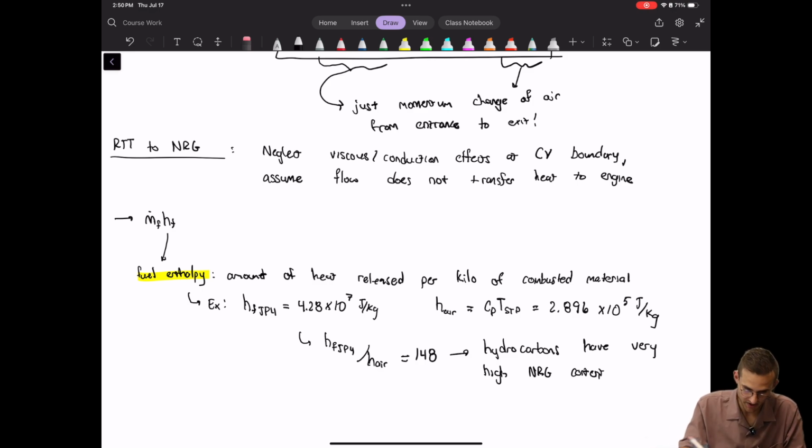I'll continue writing the equation here. So that was the left-hand side of the energy equation, the Reynolds transport equation applied to energy, that total derivative part. Then we integrate over the control surface on the other side, where you have rho times the internal energy per mass times v dot n hat dA.